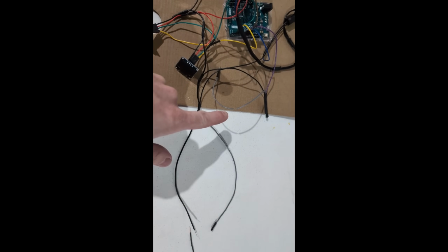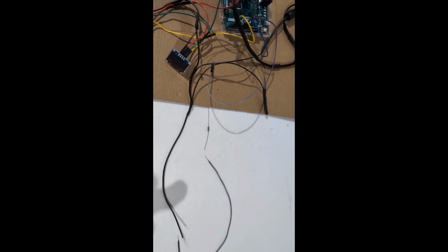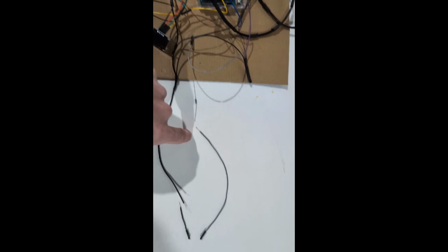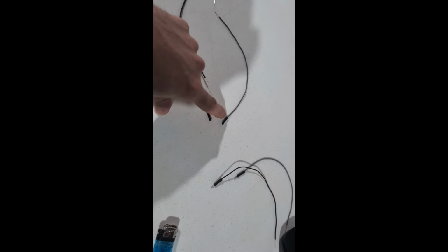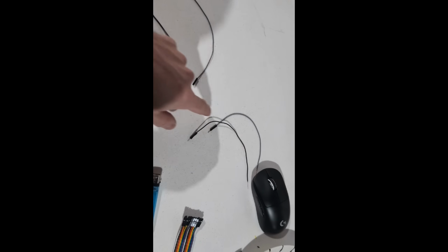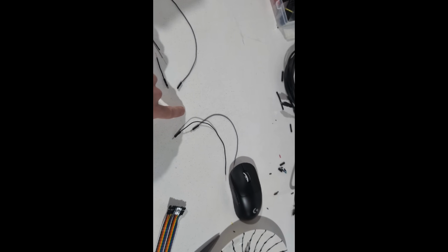that's a transistor. There's a 220 ohm resistor. That'll go between that and that. That'll go to a connector. We're just gonna actually use a quick connector. So we can actually quick connect to the mouse if we want to take it in or out to make our life easier. And this will be really handy if you ever wanted to solder into a different mouse altogether.